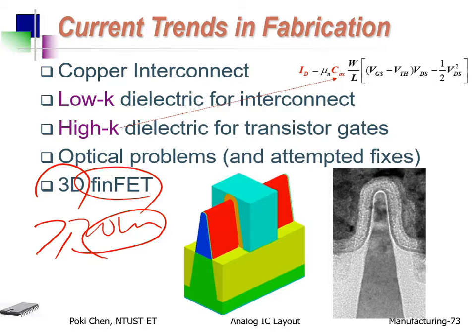Okay? But don't be too happy. Will we use FinFET all the way to 3, 2, 1 nanometer? No, sorry for that. According to the roadmap of TSMC, FinFET will survive until 3 nanometer. But for 2 nanometer, they will use the other one called GAA, gate all around. Later I will explain the structure.